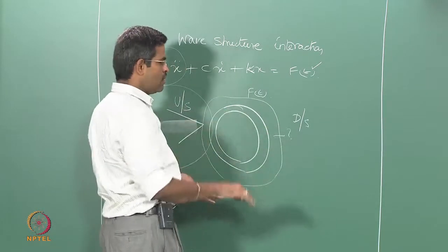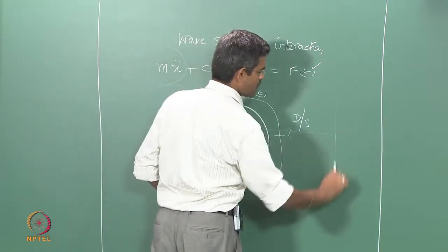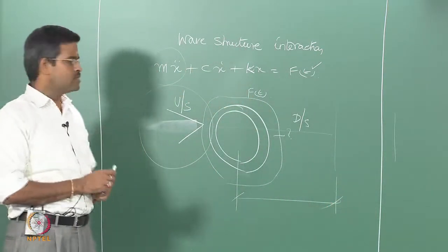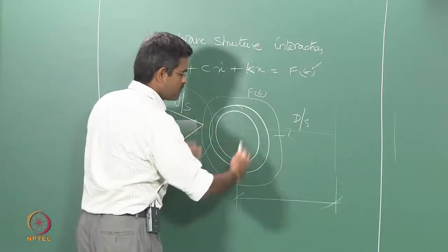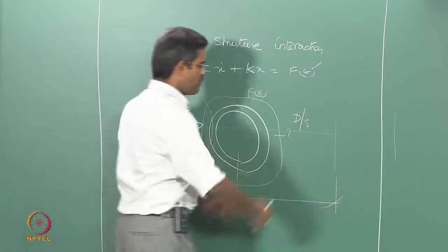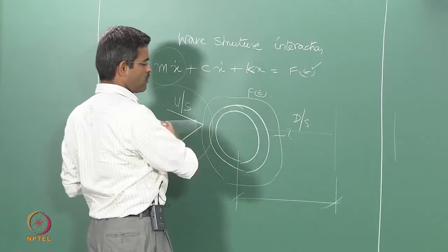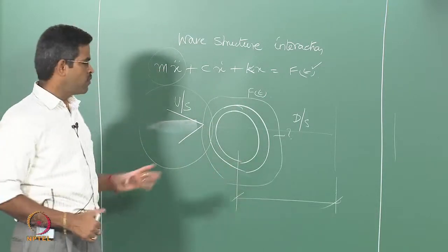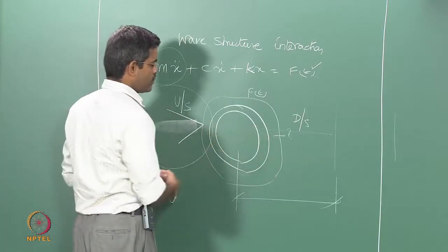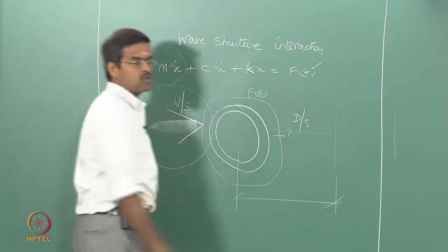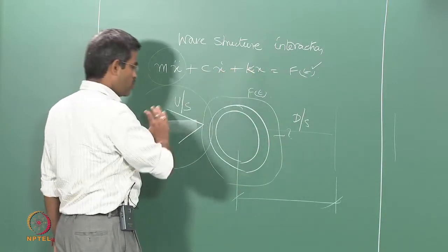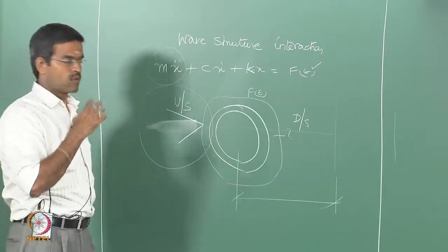However, this interference will settle after the wave has passed the cylinder by a specific length, which we call the characteristic length of the given problem. So, this is actually the boundary element of the given analysis, which we will talk about later in the coming lectures in this module. Beyond this, the interference effect of the cylinder on the wave field or the flow field will not be significant at all. So, if you want to mathematically or numerically model the behavior of fluid structure interaction, your domain should be capable of encountering the whole disturbances in the inline as well as transverse direction, numerically as well as experimentally. Okay. So, that is what the idea is.